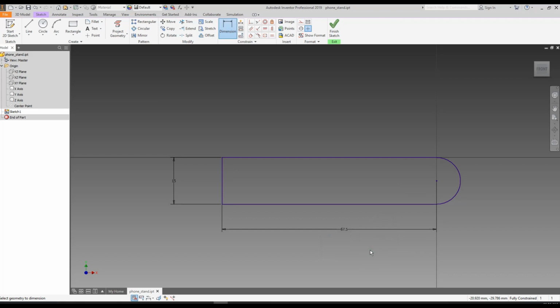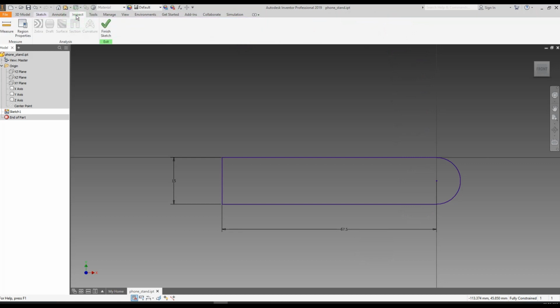And now, how do we know that this one is actually 75 millimeters long? Well, we can do geometry and math and we can conclude it, but I will show you a little bit of tips and tricks. And that is if you go to inspect. So stay in sketch, click on the inspect tab. This is a very useful thing to know. You will have a lot of use for this tool later on. And there's a measurement tool.